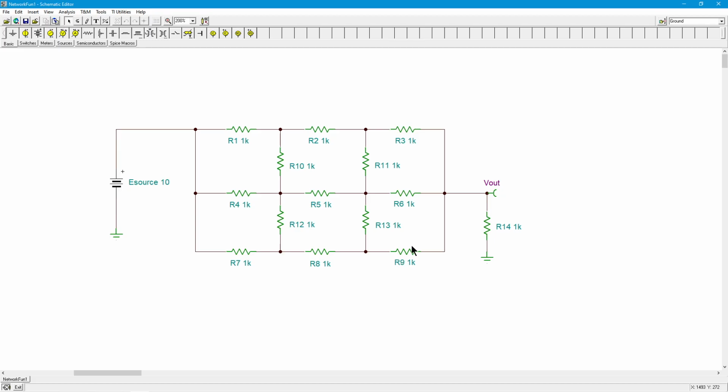But that can't be, because these three resistors all wind up at the same point. You can't have a bigger drop across this than you do across these and come up with the same voltage if this voltage over here is actually lower than these two voltages, right? There's no way that could possibly work. And you could do the experiment the other way. Mentally, you could imagine, oh, this current's a little bit smaller. It doesn't work. You're always going to get to this point and find out that you have a violation, right? It's a wire. This is one node. It can't be three different voltages.